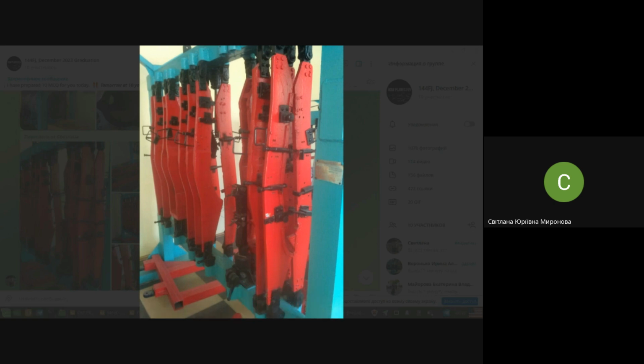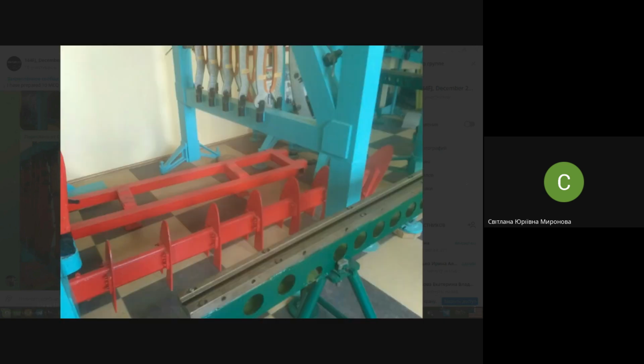All colors are telling you something, and red color says: I am a tooling for mounting the jig. The one who painted these locators brightly in beautiful colors has done a bad service to our students. Normal colors of jigs are silver-like, green-like, gray-like, bluish, something like this, but not red. Red is only tooling of second order, tooling for mounting the jig.